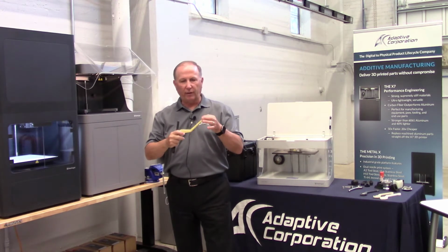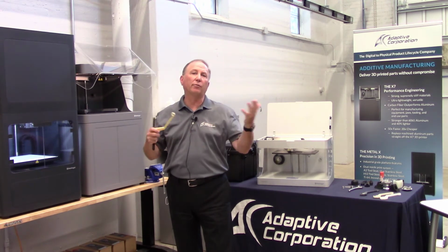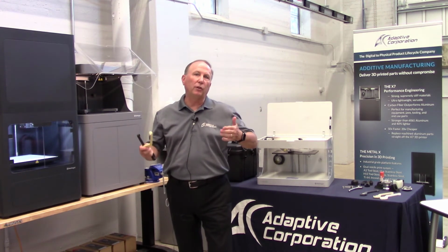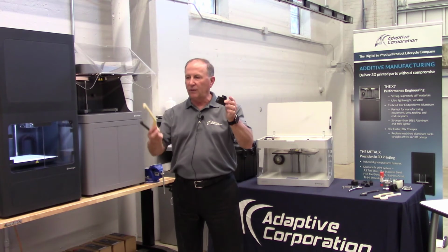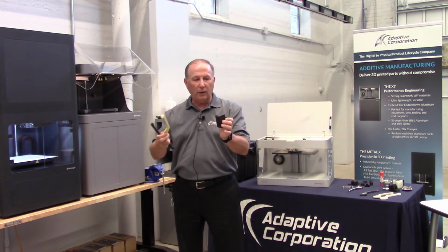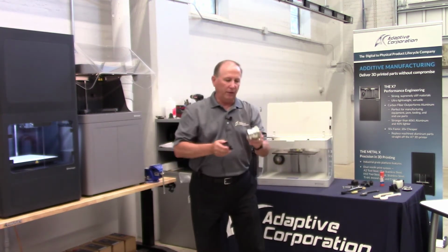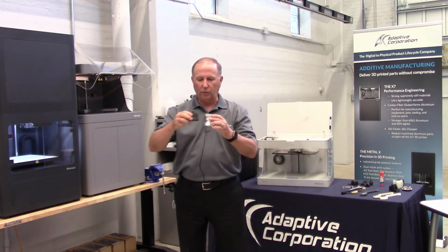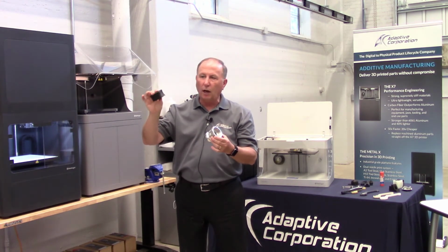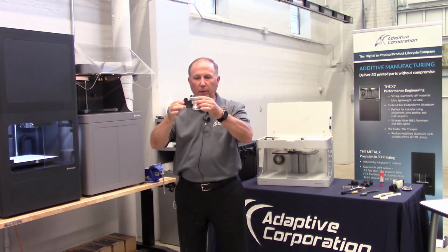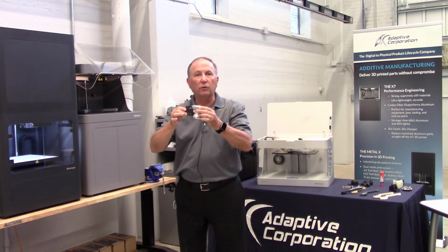By virtue of adding reinforcement material to the part, we can potentially use it as a substitute for a variety of metal applications, where in the past you might have used metal parts, for example, for end-of-arm tooling or work holding applications. Now we can 3D print those. In this example, this is a metal part that I'm going to clamp onto for end-of-arm tooling or for a jig or a fixture. By using the carbon fiber material to clamp onto your metal parts in production, the carbon fiber material is non-marring, so I'm not going to scratch your part.